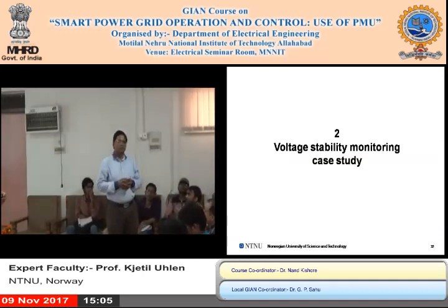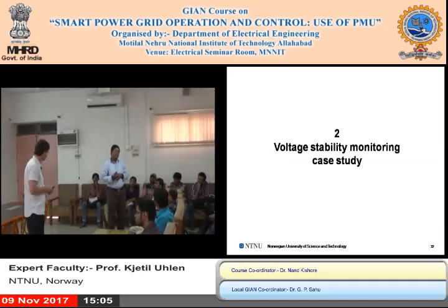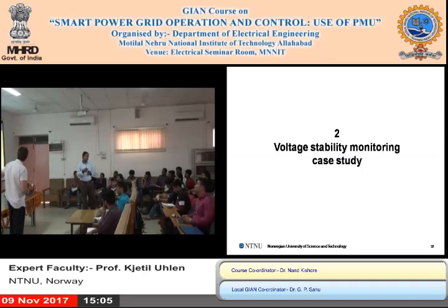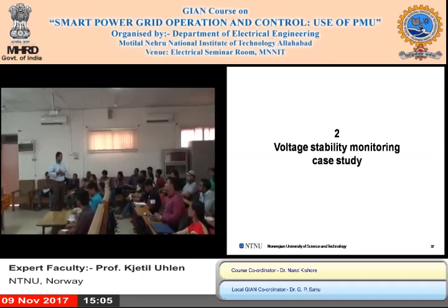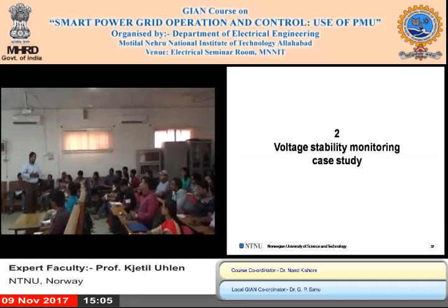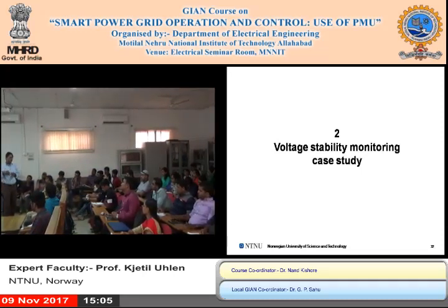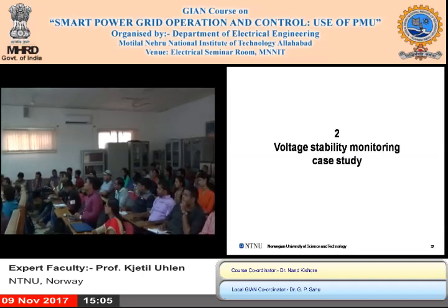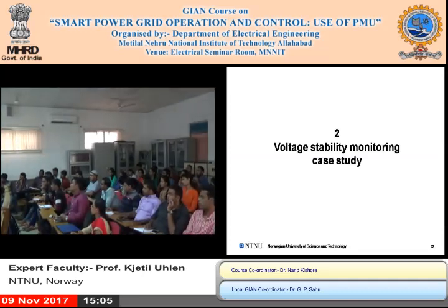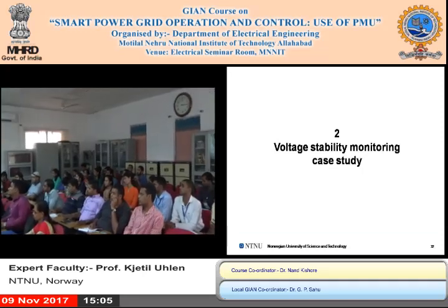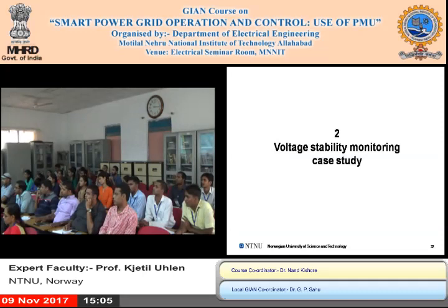The algorithm they discussed, dP by dG, is monitored as the instability index, to know at what point, as we change the load resistance, you are likely to have voltage instability and collapse. So in his master's thesis he discussed what is the best index to describe the voltage instability.